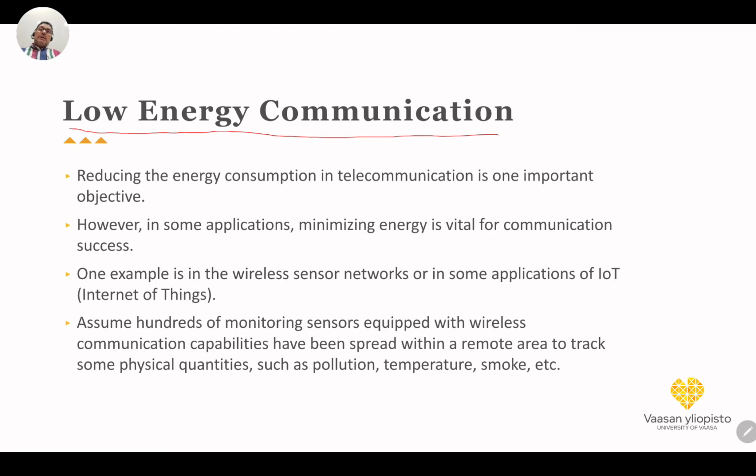So those sensors usually are small size, and they are equipped with coin type battery, and they should work for months or years. Some of them should work up to 5 to 10 years without replacing the battery. Of course they can work at a very low active cycle. Some of them send packets only a few times per day, but anyhow they should work for years. So in that sense, very low energy is very important in many of those applications.